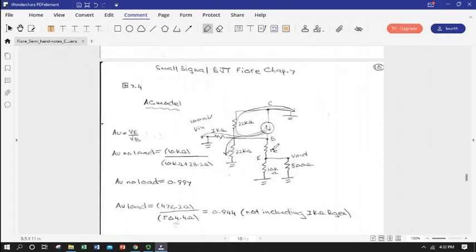So that goes into our AC model along with our load resistor of 500 ohms, our emitter resistor 10K, we got our base, fairly large base resistor, and then our divider drop and our 1K input. It's going to give us some real losses coming in. So we know our gain is V out over V in, and V out is VE, and V in is VB.